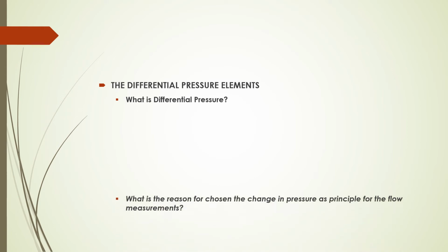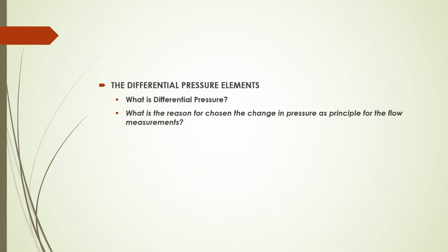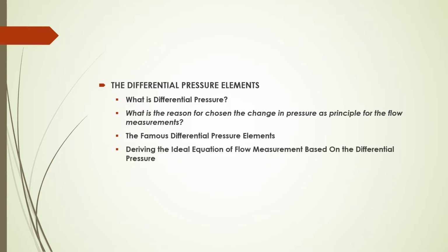In today's lecture we are going to discuss the differential pressure elements, but before that we need to discuss the following items. What is differential pressure, and what is the reason to choose the change in pressure as a principle for the flow measurement? Then later on we'll discuss the famous differential pressure elements and how to derive the ideal equation of a flow measurement based on the differential pressure.